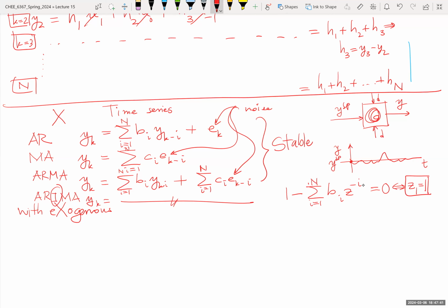It integrates values. Okay, so there is a drift here that it goes up and down. Not everything settles back to steady state. Chemical processes actually on occasion have this behavior of slow drifting. So ARIMA models are used. There is more to this alphabet soup, actually. So there are all of these models that I mentioned here. You can add an X here and make it ARX or MAX or ARMAX or ARIMAX. Okay, well, let me just write one. Let me write an ARX.